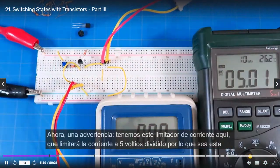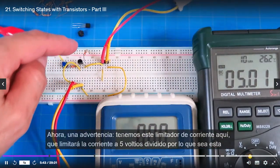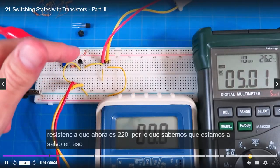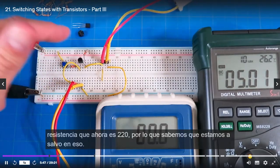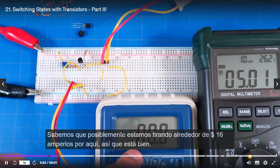Now, word of caution. We've got this current limiter here, which is going to limit the current to 5 volts divided by whatever this resistor is, which now is 220. So we know we're safe on that. We know that we're possibly pulling about 16 milliamps through here, so that's okay.